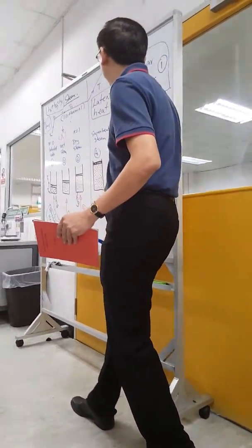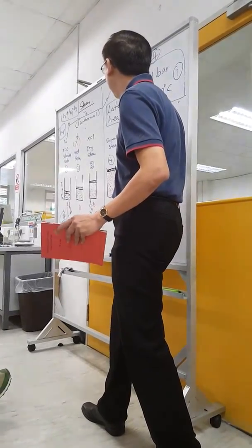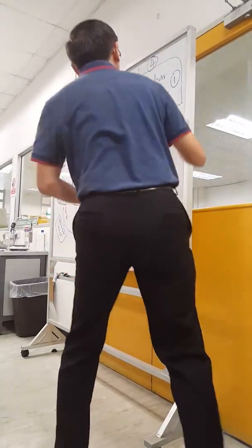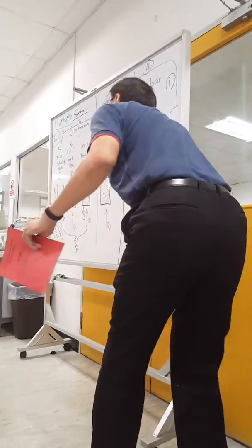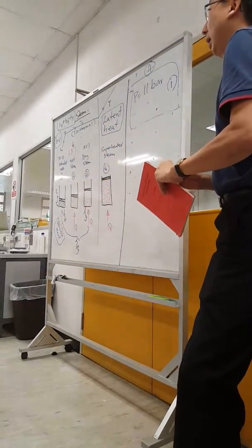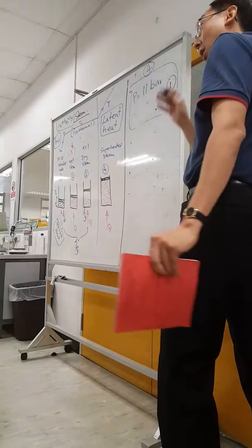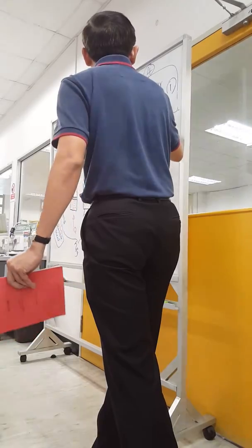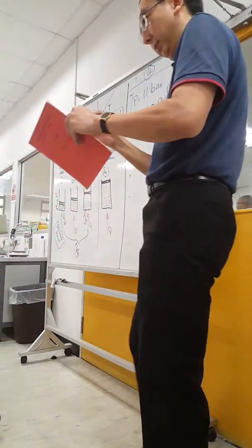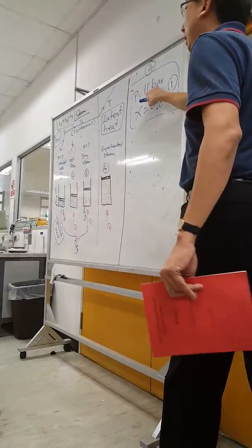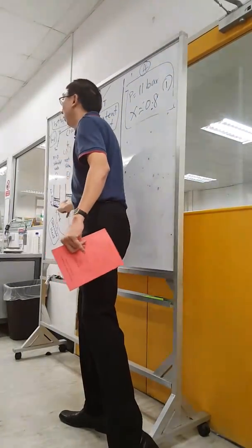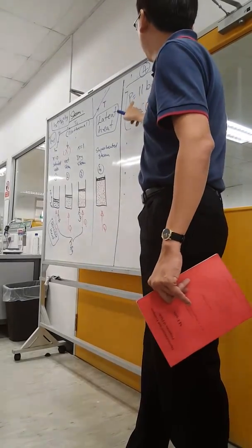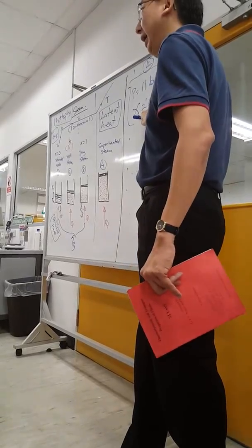Okay, so I already told you how to see what stage they are in. Now, if I give you this: water heated at 11 bar and has a dryness fraction of 0.8. That is stage 2. So when I tell you this, you know that this is another stage. This is wet steam. It is now totally steam, but 80% dry, 20% wet.